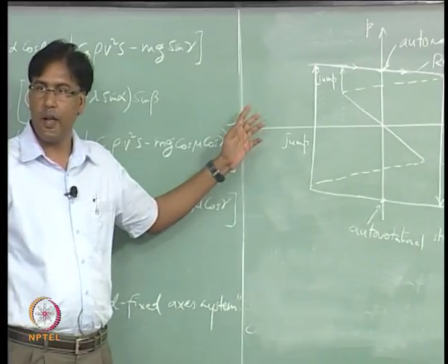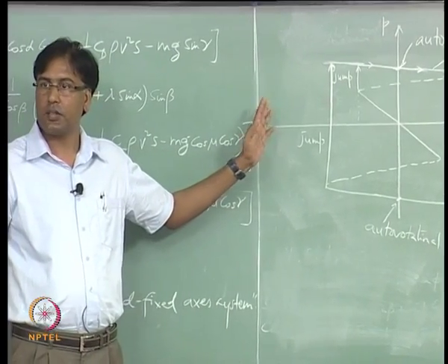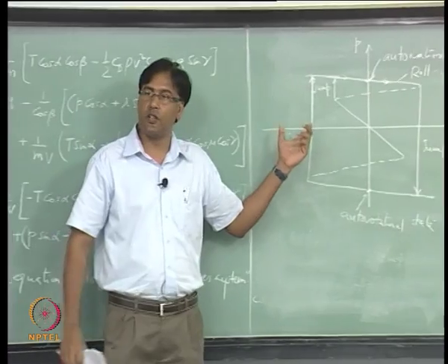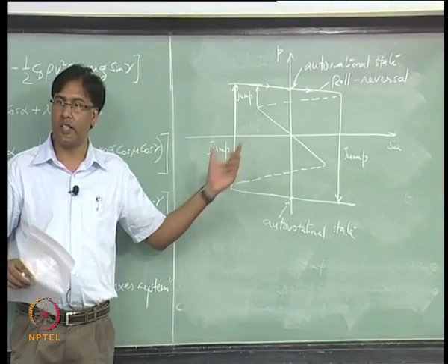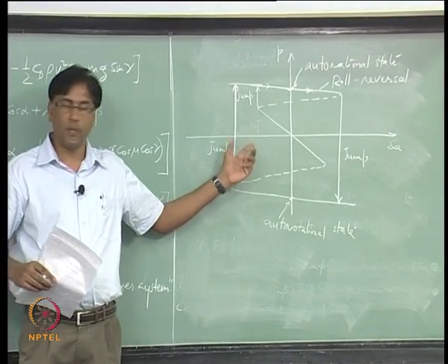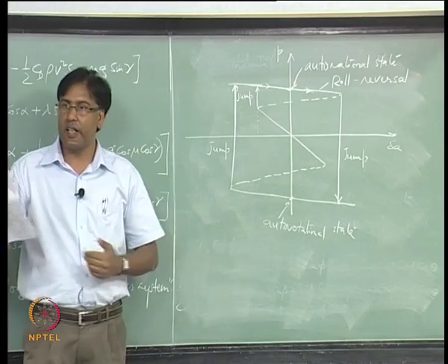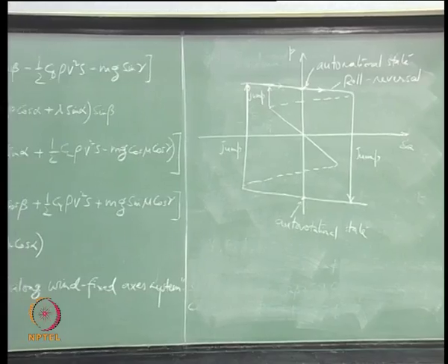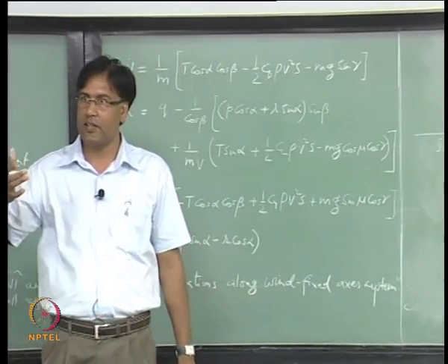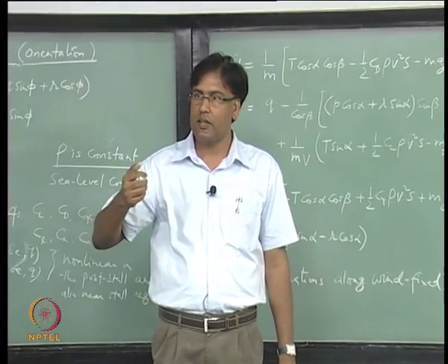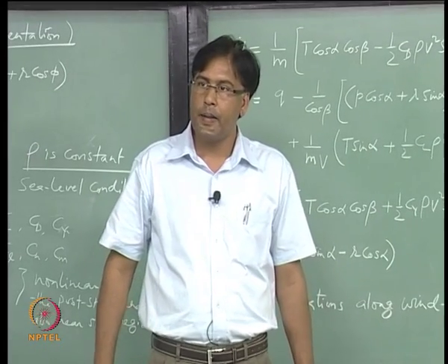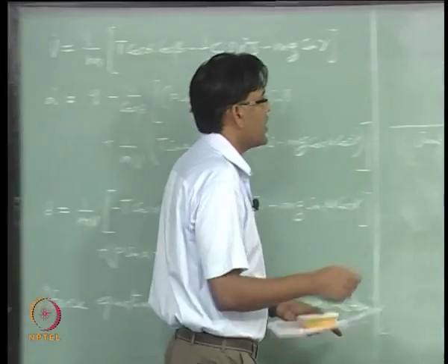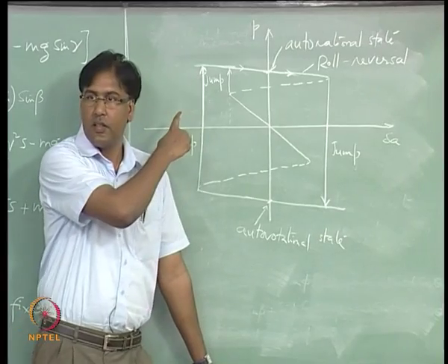But just because it's nonlinear, it is going to give rise to side slip, okay, when this happens. So, beyond this point you have a large increase in side slip, and side slip can also contribute to the roll. Look at the vertical tail. At that point the solutions become unstable, okay.